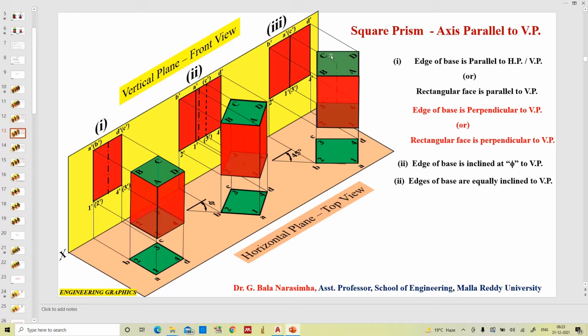So in the same line we are having three different types of lines. One is a visible line, second one is the center line, third one is the hidden line. So according to the line priority concept, the first priority will be given to the visible line, second priority will be given to the hidden line, third priority will be given to the center line.